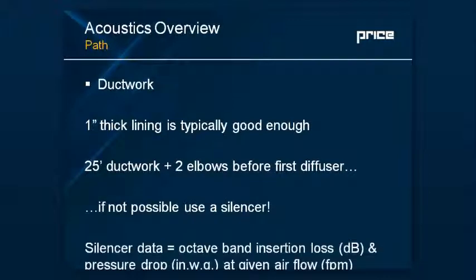And finally, just make sure that the data provided for a silencer and listed on the schedule gives you the octave band insertion loss data, again, between 63 and 8,000 hertz, the pressure drop, and what the airflow is.